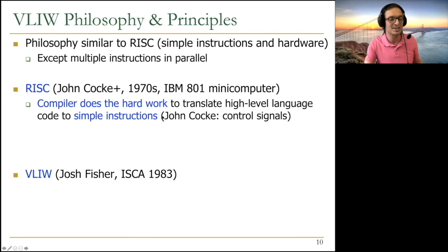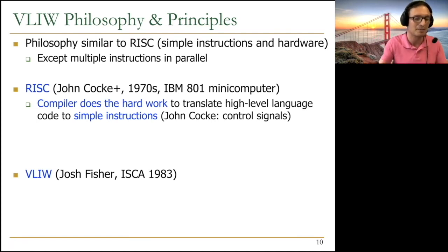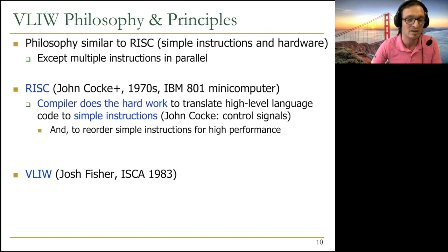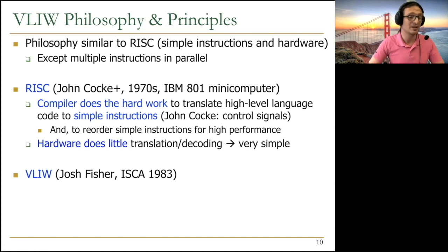Not complicated instructions like string copy, for example. That's too complicated. You want to add and XOR, simple arithmetic and bitwise instructions, not even multiply, as I said. And of course, the compiler needs to reorder simple instructions for high performance to do this. And the philosophy is that hardware does little. It does little translation and decoding. It stays very simple, no dependency checking as much as possible, and no reordering of instructions. But as we discussed earlier, this is not an easy task to do.